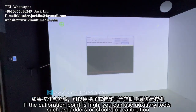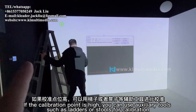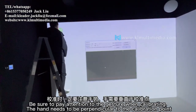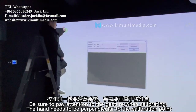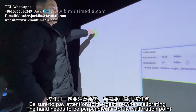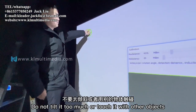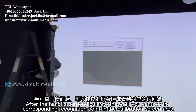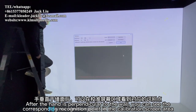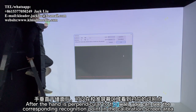If the calibration point is high, you can use auxiliary tools such as ladders or stools for calibration. Be sure to pay attention to the gesture when calibrating. The hand needs to be perpendicular to the calibration point. Do not tilt it too much or touch it with other objects. After the hand is perpendicular to the wall, you can see the corresponding recognition point in the calibration screen area.